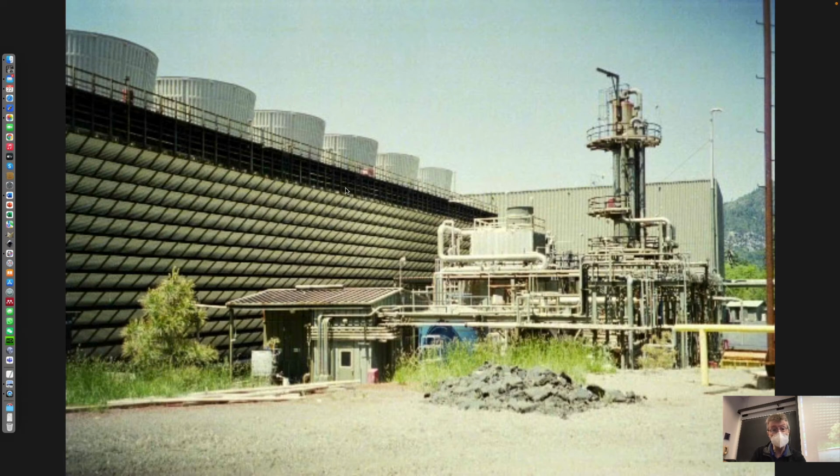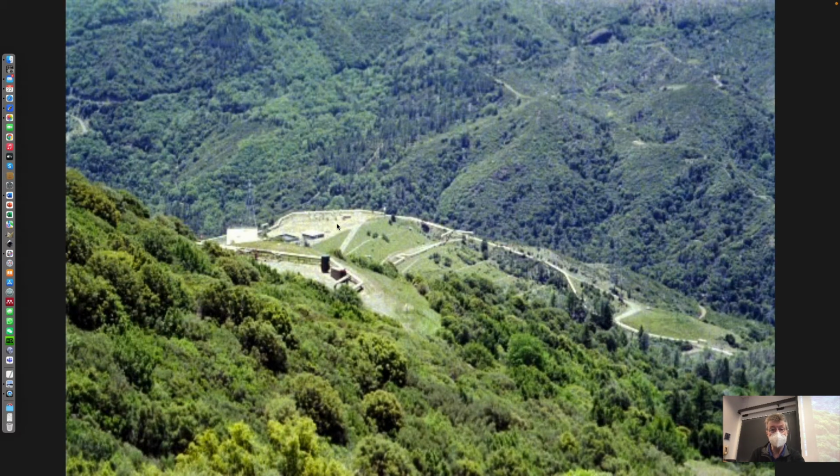This is a condenser, the same as we saw in Taupo in the previous slides. You push cold air up through these with little propellers in them. You have water circulated in a piping system, just like a radiator in a car with lots of surface area, so that the relatively cool air, probably 20 or 30 degrees centigrade in California, cools down the hot waters and allows you to re-inject it.